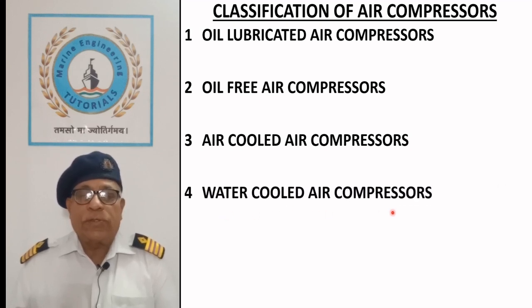Water-cooled air compressors. Water cooling is preferred for large compressors, which reduces carbonizing of lubricating oil due to low temperature of cylinder liner and valve cover.